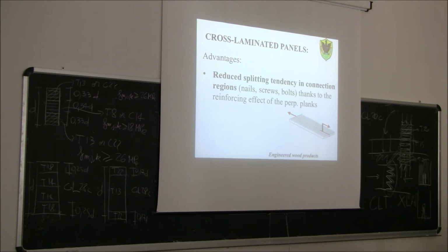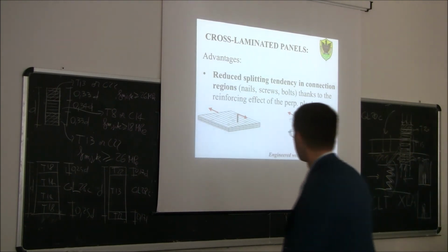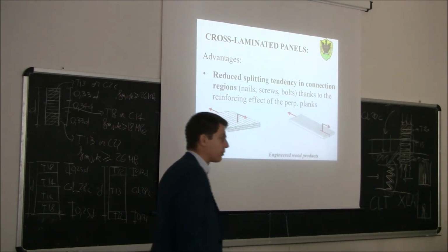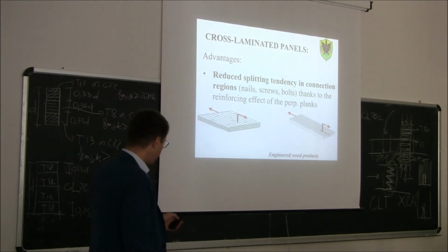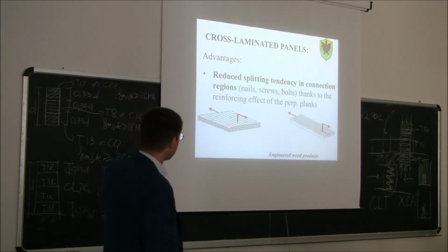Due to the very low strength perpendicular to the grain. So this is the typical failure mode for a glulam member connected to a dowel. Now, let's think about what would happen in the case of a cross-laminated timber panel. We have the same hole going through the panel, the same dowel, then we apply the tensile force. Is this kind of failure still possible in this case?